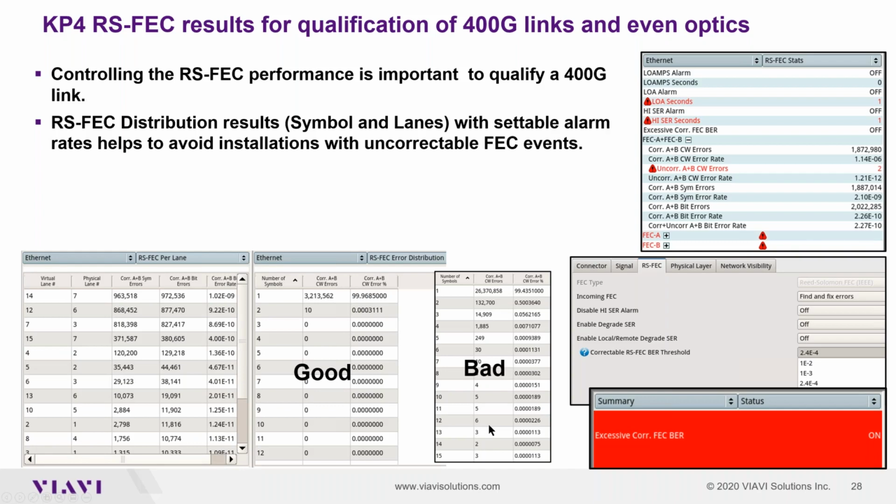So first qualify your optic, which you will later on use in the local system. Test it in the tester. What is the distribution? Is it good or is it bad? If it is good, okay, take the other one, check it, make the connection, check what you receive, and if it's still in a good range, okay, you can bring it into operation. And probably you have to do it from A to B and from B to A, so your local connection. It sounds like a lot of work, but the experience is that this can happen.